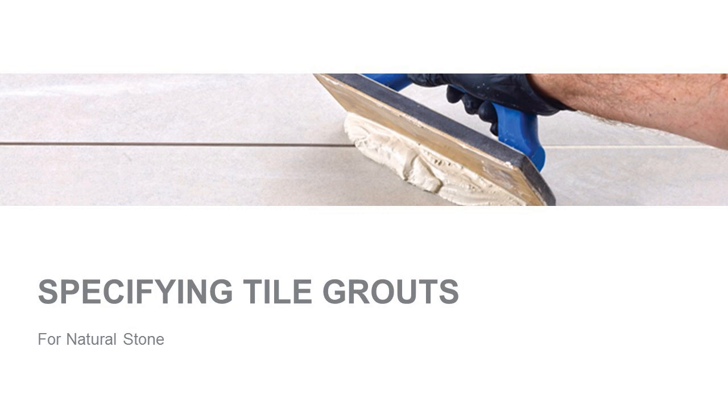Specifying tile grouts. This is the final, most visible part of the fixing process and is the most important to get right. Beautiful stone tiles will look fantastic when grouted well and with the right product. As with all tile mortars and grout selection, it is equally important to consider the parameters and the tile in the finish environment. Although dispersion or ready-mix grout tend to be popular within the DIY sector, professionals will use a cementitious or reaction resin system due to a number of issues relating to ready-mix grouts.